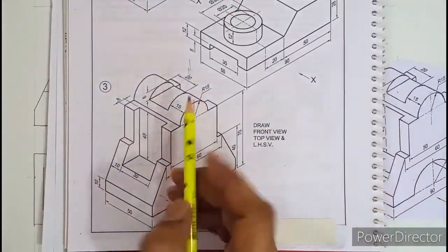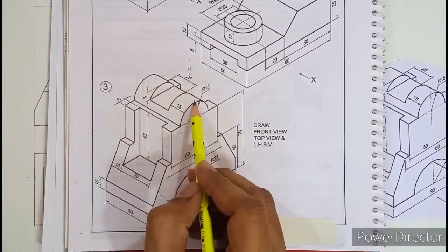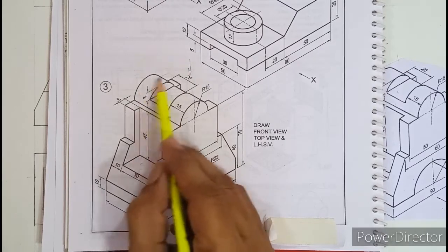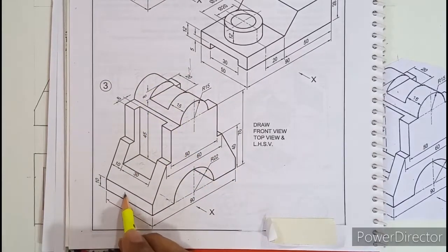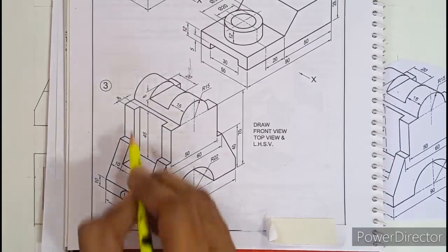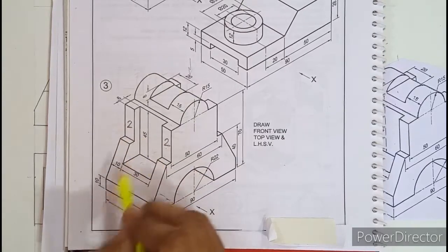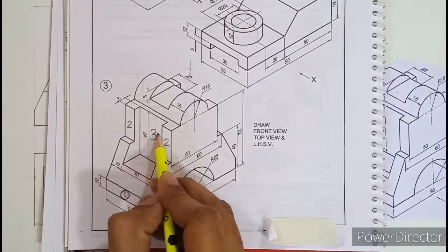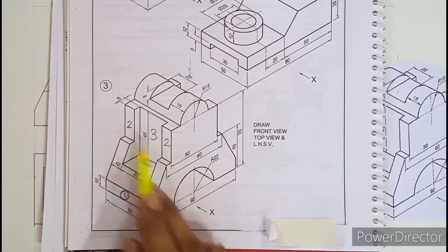So when we start with the side view, this top portion I was talking about was a C type. This we can draw at the end also. Let us start step by step. So the first nearest flat surface is this one, which can be seen. Second are these two flat surfaces in the side view which can be seen. Third is this 45-degree flat surface. So let us draw these three flat surfaces first of all, first, second and third.